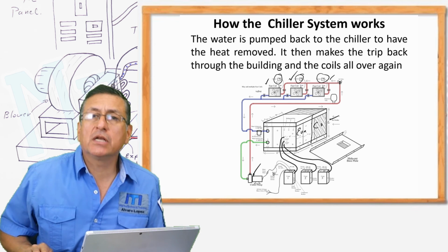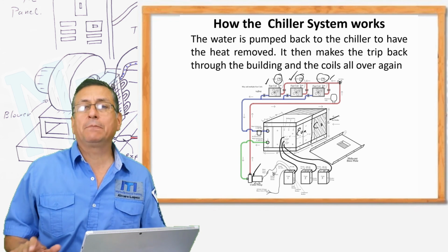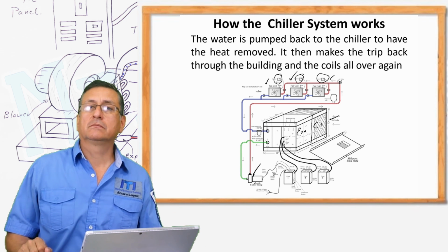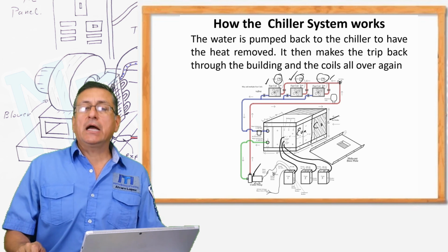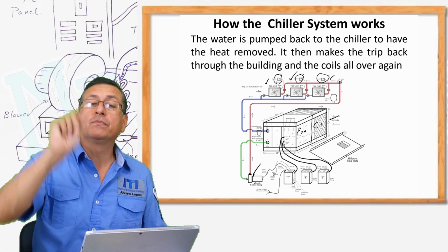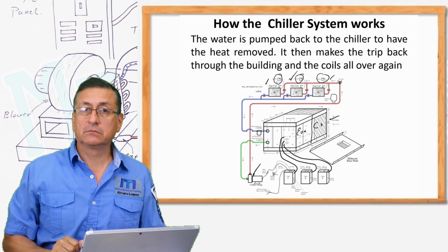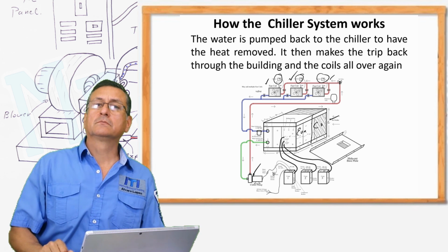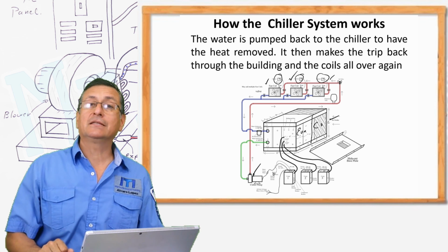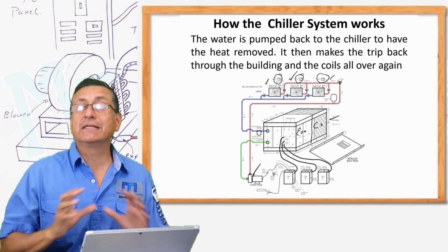The chilled water normally is fresh water plus glycol, 50-50. The same coolant that you use in your car. And in each air handle you have one thermostat, to manage that handle. All right? You like it? This is a wonderful system, the chiller system.